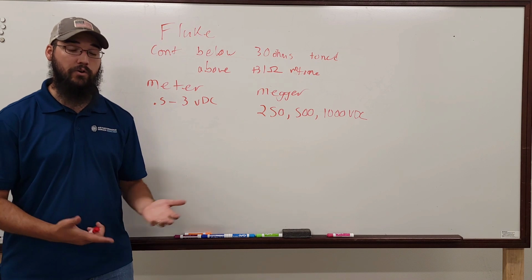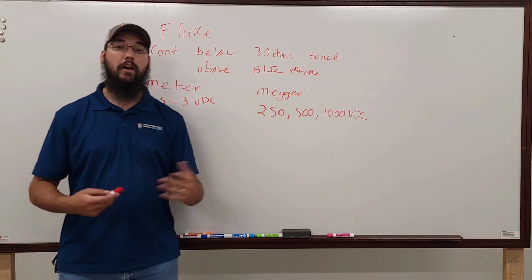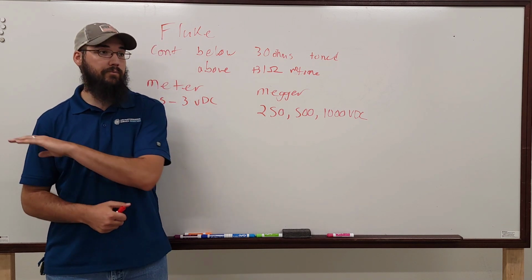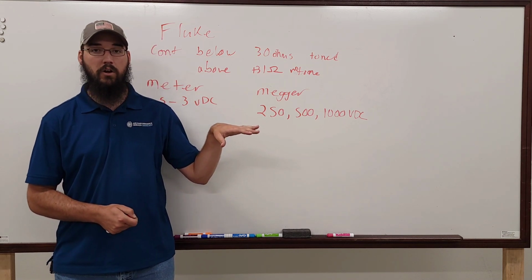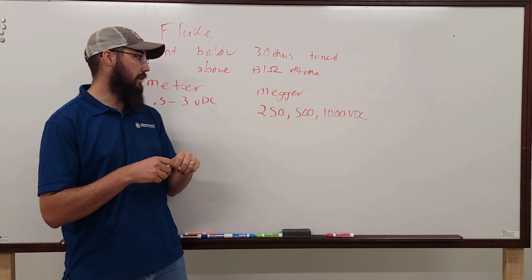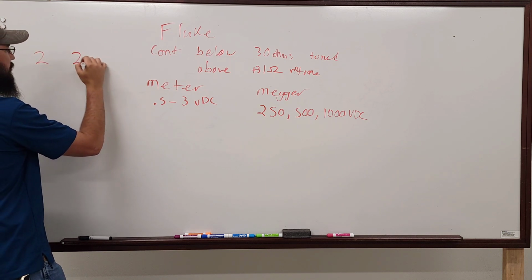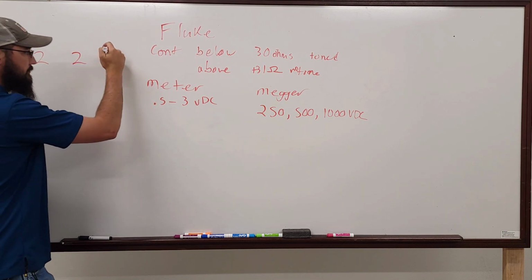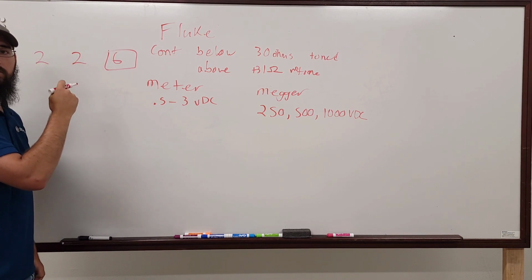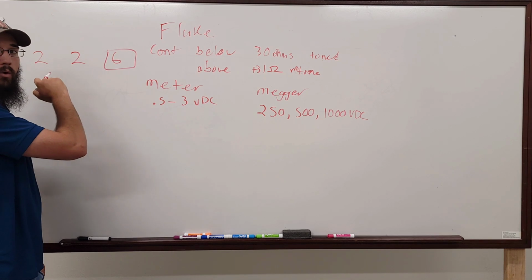Which on a 3-phase motor, we haven't talked about that. I probably should have covered that in the beginning. A 3-phase motor, you're going to have the same ohm reading across all legs. If you've got one leg that's, you know, if you got a 2 ohms, and then 6 ohms, something's wrong. Something shorted, something screwed up, or these are shorted and why they're lower.